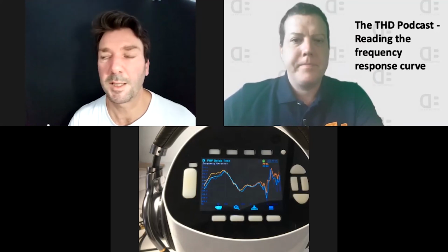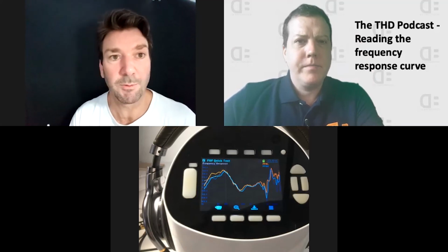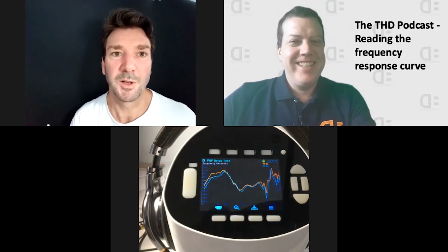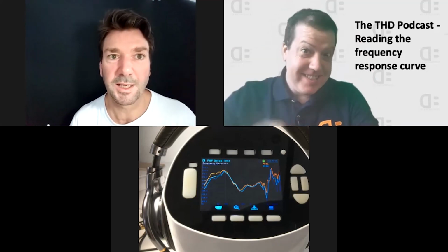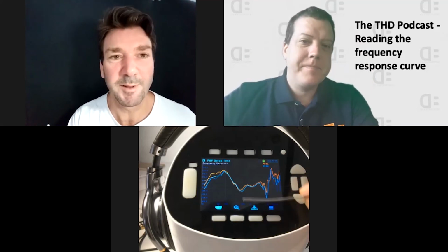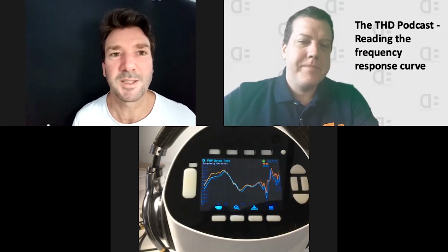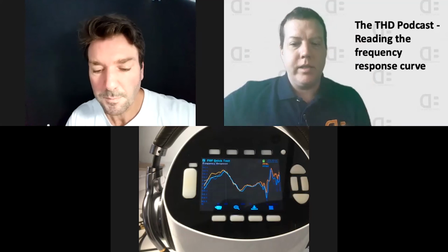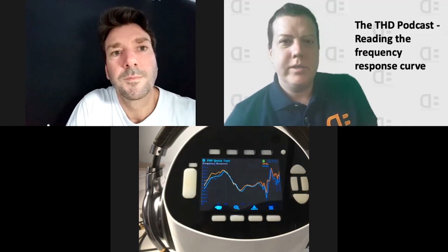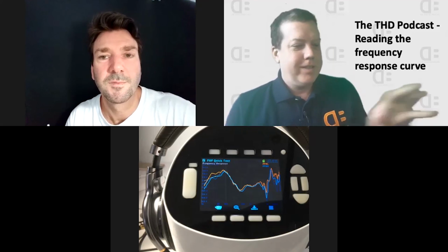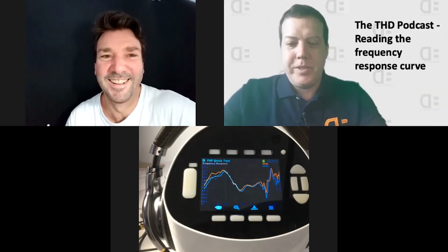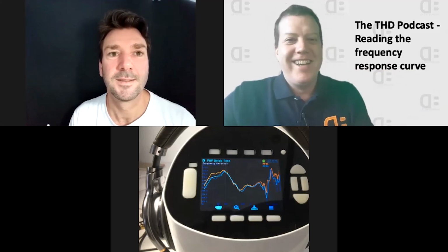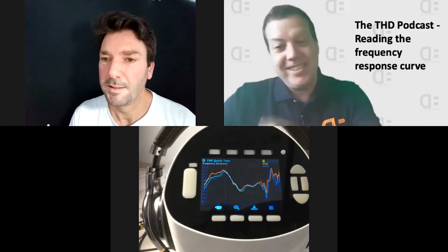Yeah, exactly. But if you have a target that you want to go for, you need to have that in mind when you're doing the industrial design too, because certain things will be fixed into it, like the overall size that you've got in your front chamber. It's just going to govern some of the mid-range characteristics. There's nothing you can do about it after that, or the size of the driver. So many things in audio, like the battle between industrial design and acoustics, is who leads it. A lot of it's left up to, okay, here's the cavity you've got to work with, go fix it, acoustic engineer. That's a lot of what happens. So anyways, that's just the reality.